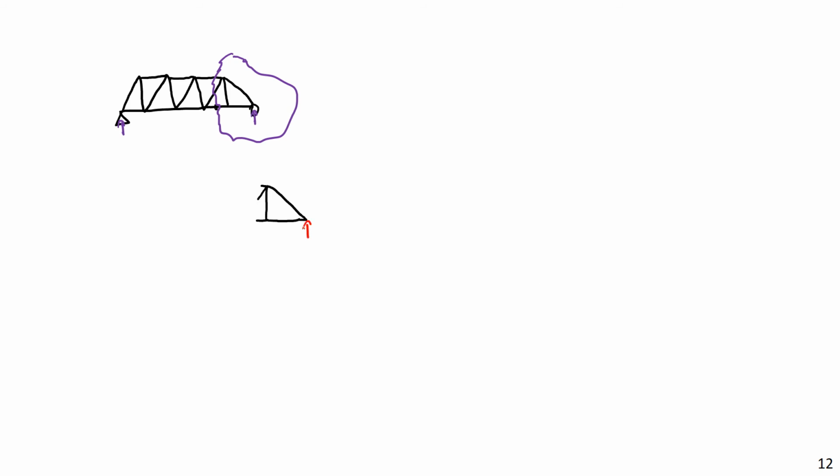So we have our reaction force here, and you'll have the forces that we're solving for here. Well, actually ultimately we were only interested in this one, and then I would apply static equilibrium to solve for whatever forces I wanted. Now, because I was interested in this force, a great way to do this would be to take moments about this point. Then I wouldn't have to solve for these unknown forces. I could just jump directly to the one I was interested in. And that really is the basic idea of the method of sections.